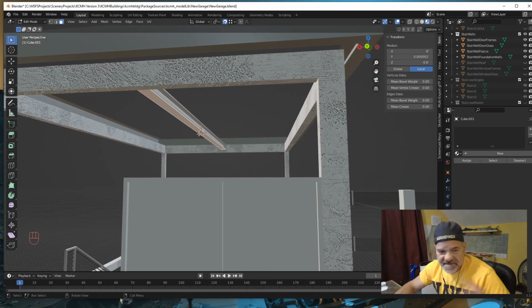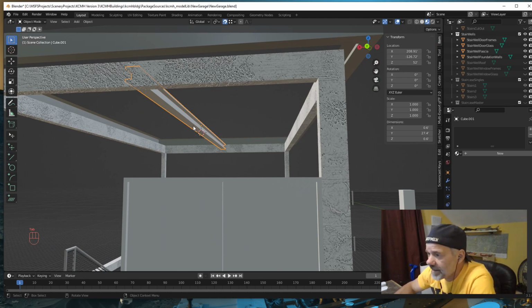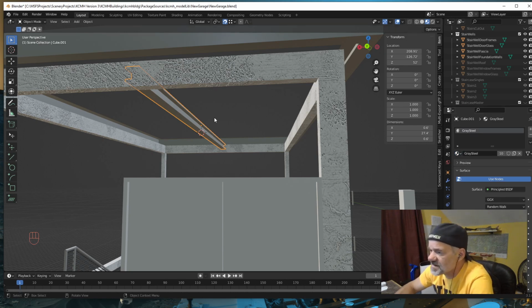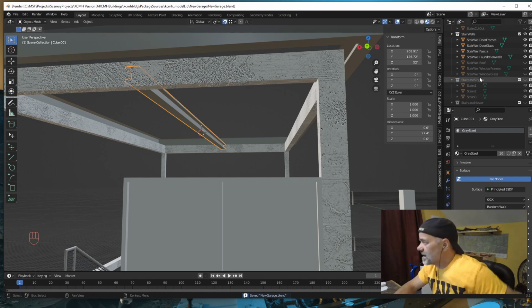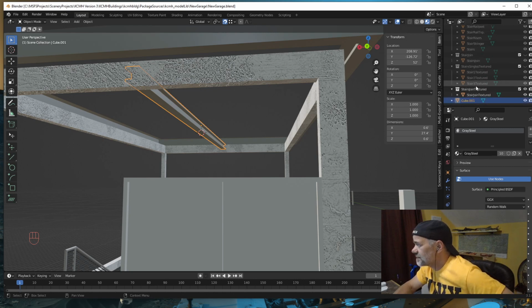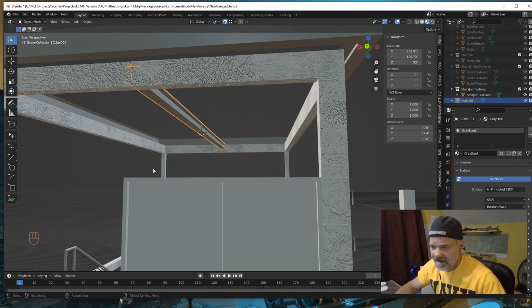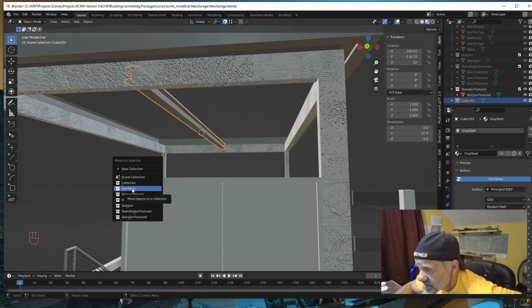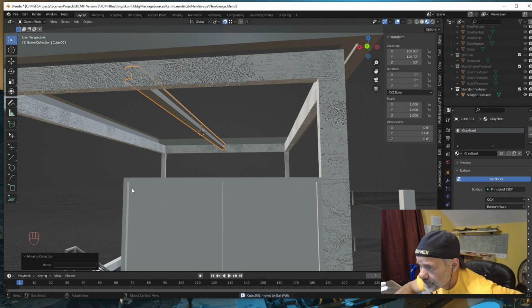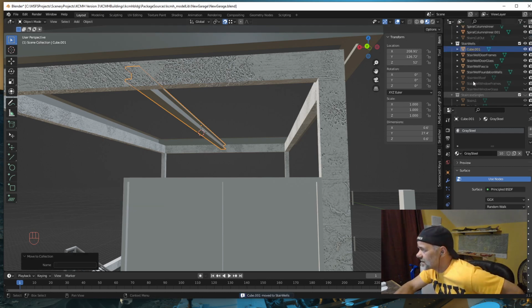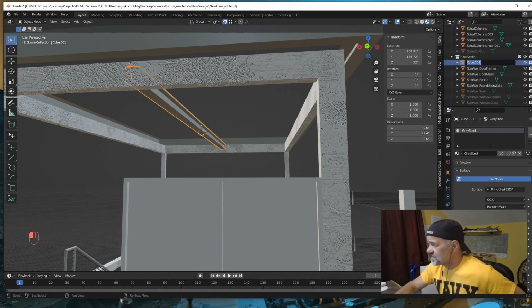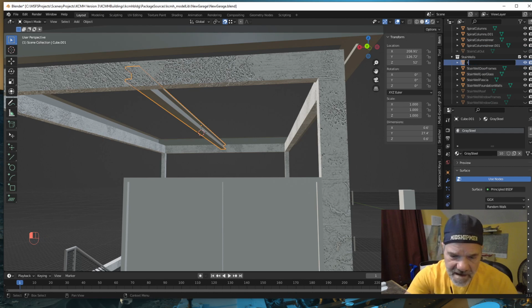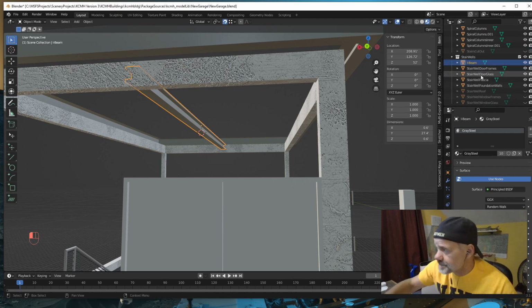With that selected, get out of edit mode, and let's give our I-beam a texture. So we're going to make that the gray steel. There we go, just like that. Do a save. All right, now at our point, oh, we need to take that and hit M and move this to Stairwells. There. So that should move our cube to our stairwell collection, and we'll call this I-beam. There we go.